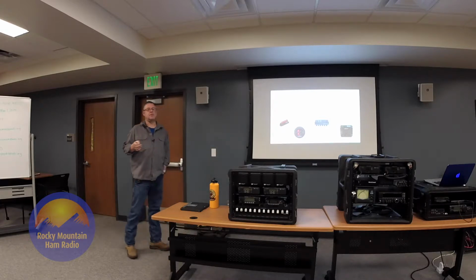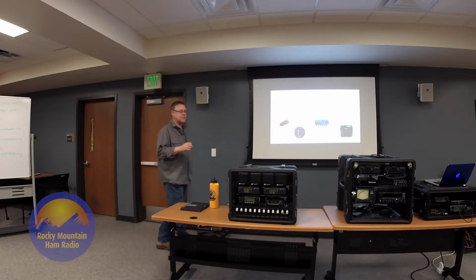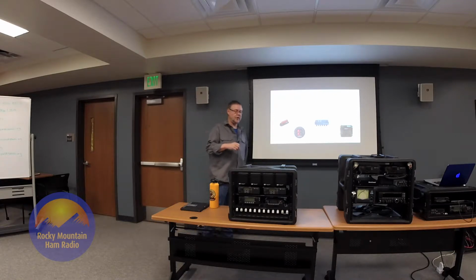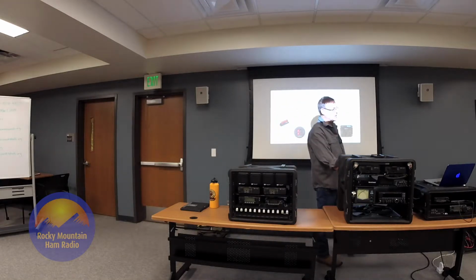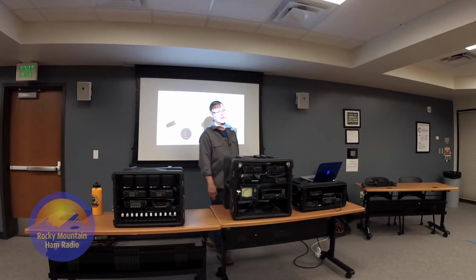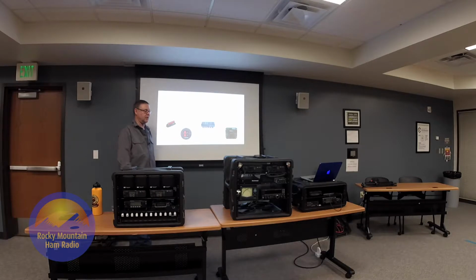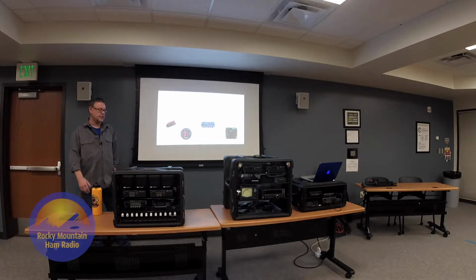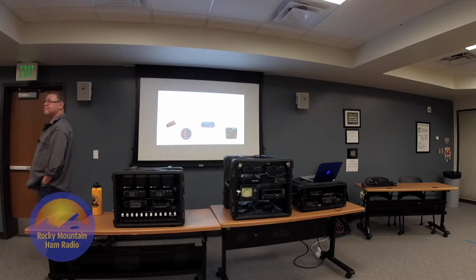So make sure you have fuses, because you would rather have the little fuse go than your whole radio get toasted. But another thing about John's open design that's handy is, when he blows a fuse, it's 2 seconds and he's back in operation. This one, it's 4 screws and poking around trying to find my rig runner in there without taking the whole thing apart. That's why the rig runner with the light behind the fuse is so nice.